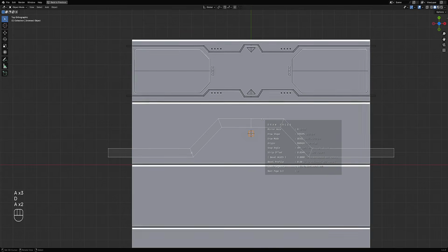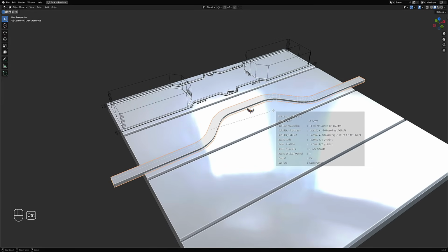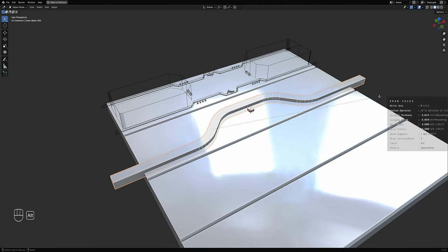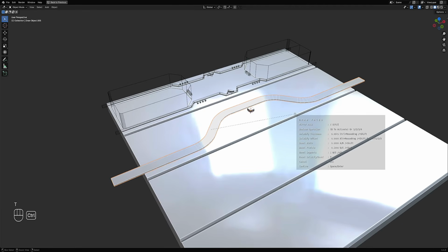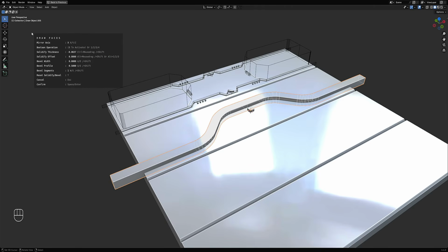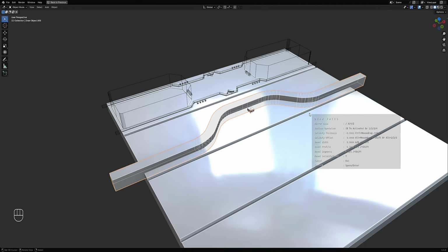Use the AD hotkey to increase the bevel, Control mouse drag for the depth, Alt for the offset, T to reset. So it's all written in the UI helper, the values for the parameters and the way to activate them.